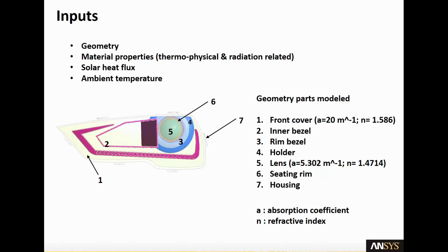This case uses an automotive headlamp geometry modeled in an air volume. Solar heat flux is given as an input and the radiation is modeled through the air volume, front cover, and lens. This is precisely the collimated beam-style irradiation in which the Monte Carlo model excels. The goal of the simulation is to predict the location of any thermal hotspots which occur from the solar rays being focused through the lens of the headlamp assembly.